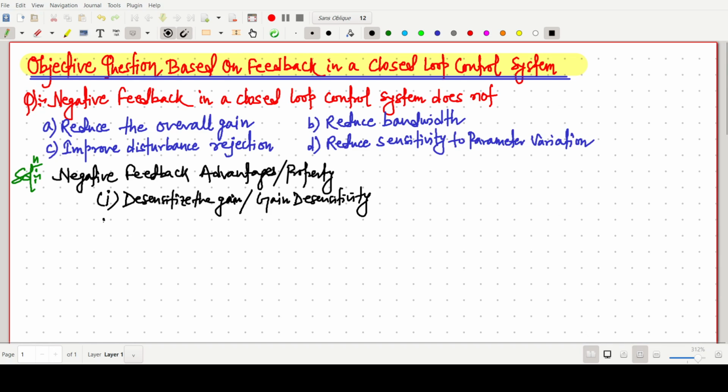For more detail you can check out my video related to feedback: what is gain desensitivity? Next one is bandwidth extension. In negative feedback the bandwidth of the overall system will be increased. Number three, we can say interference reduction, or we can say the reduction in the noise.